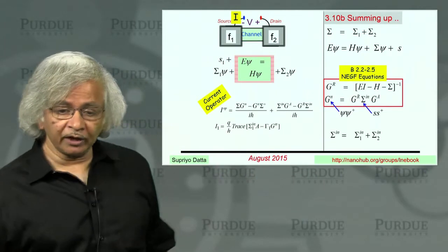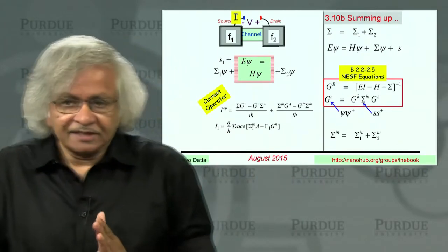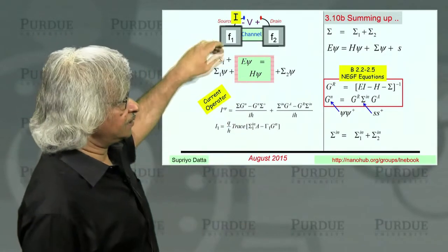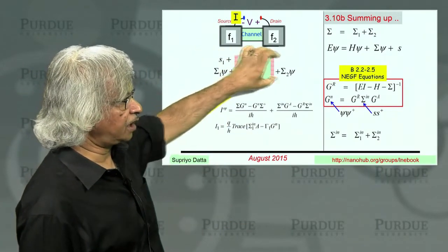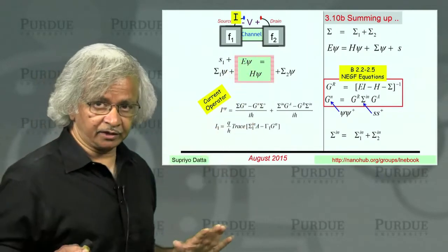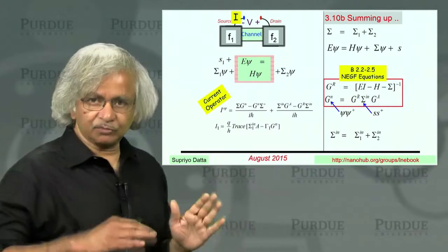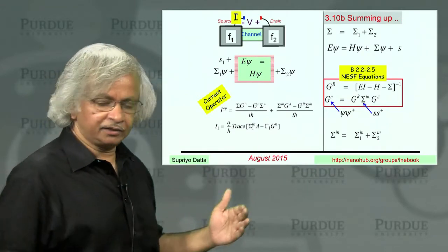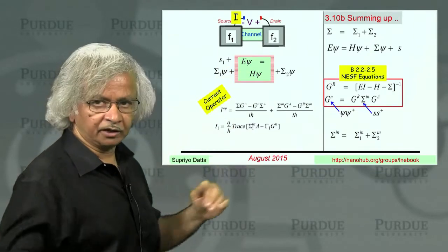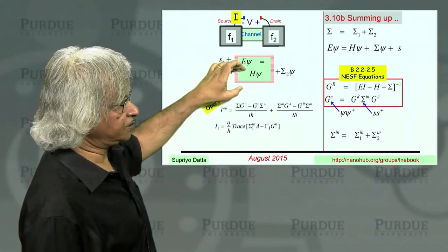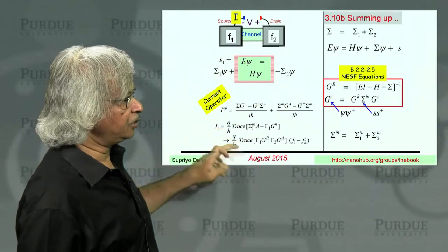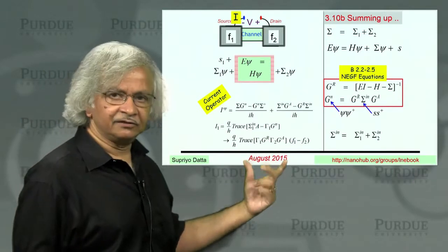And for coherent transport, which is a subset of the problems we want to consider. So coherent means the only sigmas are associated with the contacts, and you ignore all interactions within the channel. That's coherent transport. In general, of course, we are interested in non-coherent transport, where you also include the interactions, which we have also talked about actually. But for coherent transport, you could simplify this equation into a different form that's convenient.